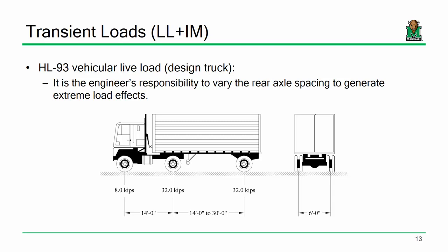But when you're getting into that level, like if you were actually doing a full-blown 3D computer model, AASHTO will tell you how to apply that load. It will say that, let's say this front wheel of 4 kips, must be applied over a 10-inch by 20-inch area. That's the contact area. So you would calculate your pressure and then put that on your finite element model, or, if you're doing this 3-dimensionally. Okay. So far, so good?